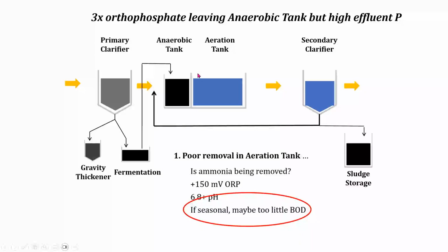And if that number is low teens, 13, 14, somewhere less than 20 milligrams per liter, maybe you've removed all the BOD here and you've got these energized PAOs, but to grow, they need building blocks, right? The organisms, the cells are made out of components that are in BOD: carbon, nitrogen, oxygen, phosphorus, sulfur, all of these components. And maybe there just isn't enough Tinker Toys to make the cell. So that's a good test to do.